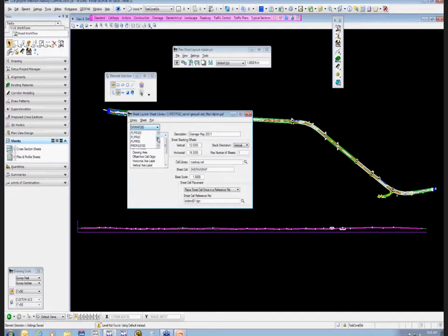Let's see. We're going to work on a plan and profile 50. I just want to go through these settings, and I'll also look at some different options that may be in plan sheets, because we've got the plan and profile, we have just plain profile, and we also have where you can dual clip or single clip just plain plan sheets. But I want to look at the plan and profile for right now because it gives me pretty much everything I need. General settings, most of the time you should not have to change anything that's sitting in here. It gives you the description, the size of the sheet. This is at a scale, not size of the sheet. This is the distances that it's going to use when it stacks your plan sheets into the file, if you have placed more than one per file.